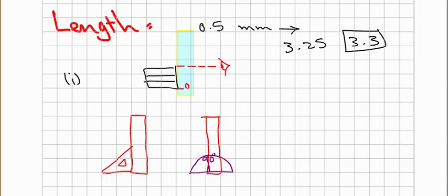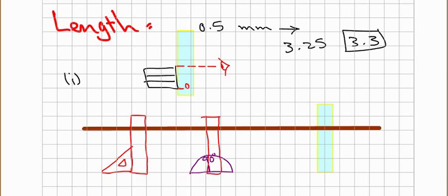Or you can use a spirit level just to make sure that something is vertical. And the same devices would be used to ensure, say, another ruler is horizontal like this, by measuring the vertical height from the bench. Right now I can use the set square and the ruler to check the vertical height along the meter ruler being suspended.